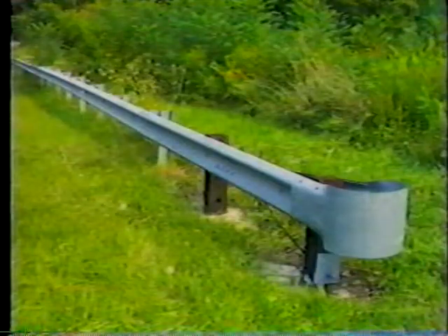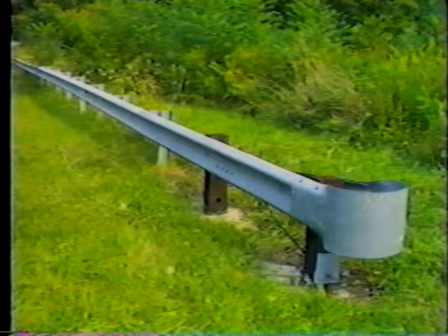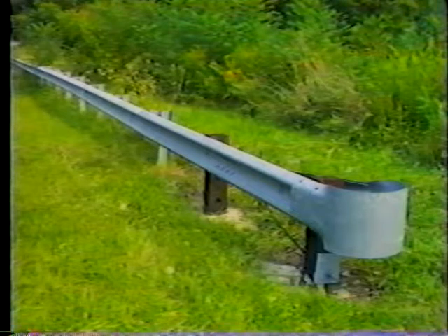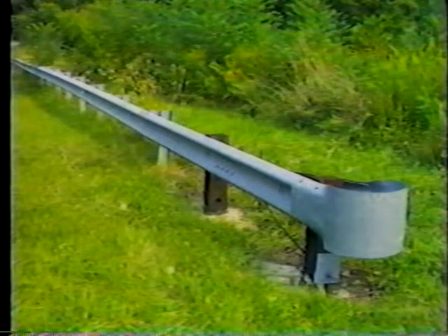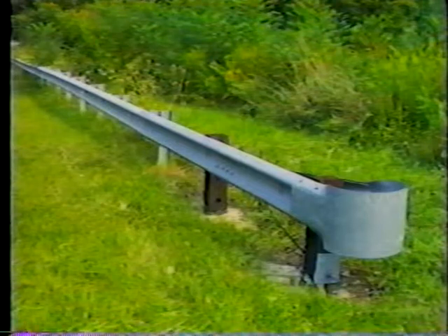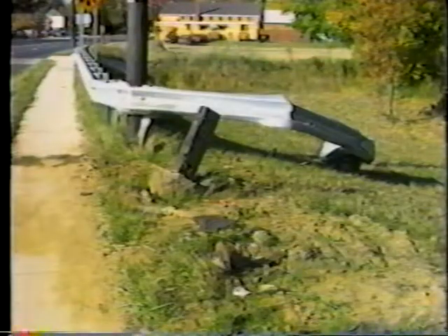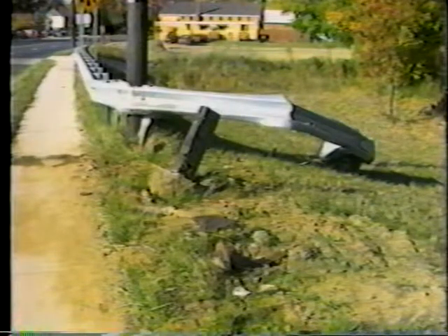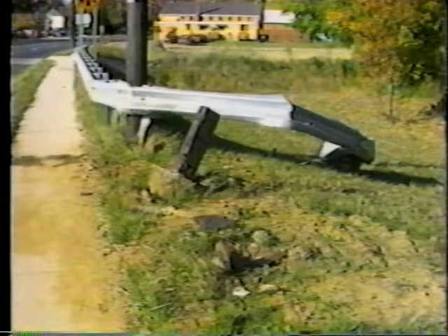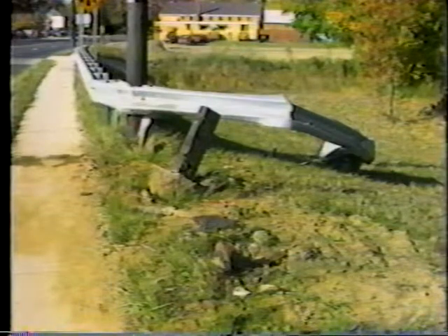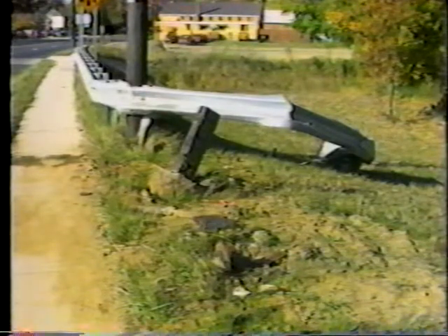Now to the systems. The breakaway cable terminal end treatment is designed to work with W-beam barrier systems, but can be transitioned to work with the tri-beam through the use of a commercially available transition piece. The roadside barrier breakaway cable terminal, or BCT, is designed to break away at the first 2 posts and allow the vehicle to accordion the W-beam and pass safely behind it.